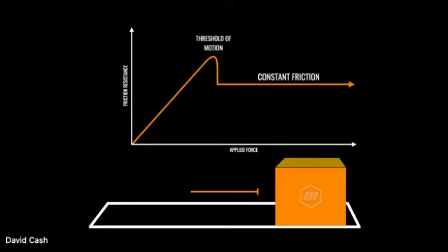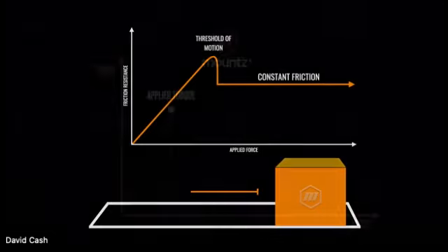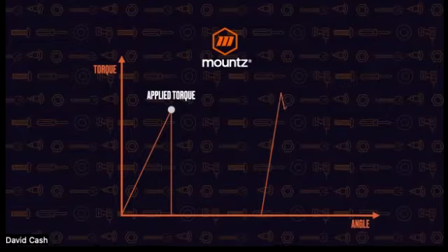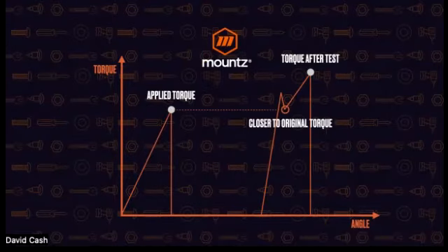And so in this case, when we're trying to use our first movement test, we actually may generate a higher torque to get that fastener started. And then after about 3 degrees of movement, we may see a drop. Depending on where the auditor stops, the wrench will read whatever the torque is after the specific test. But the typical value we want to measure is, again, between 3 to 5 degrees of movement. And that can give us a good representation of what the applied torque was at the moment of the assembly process.